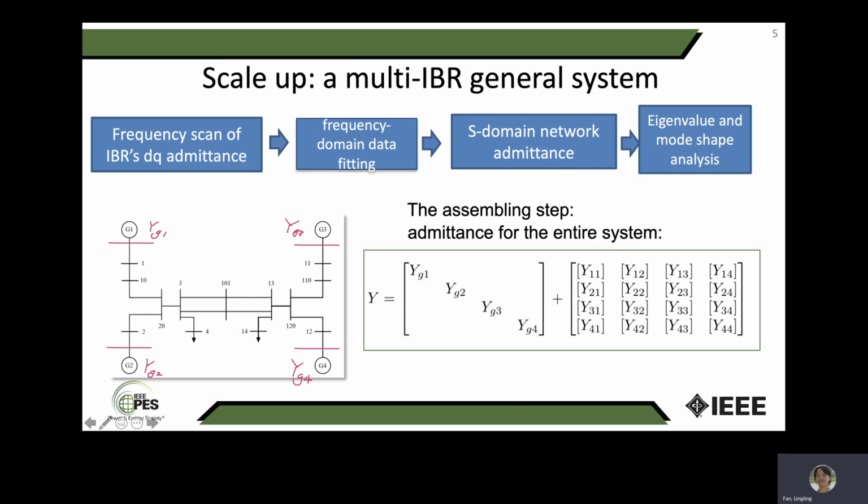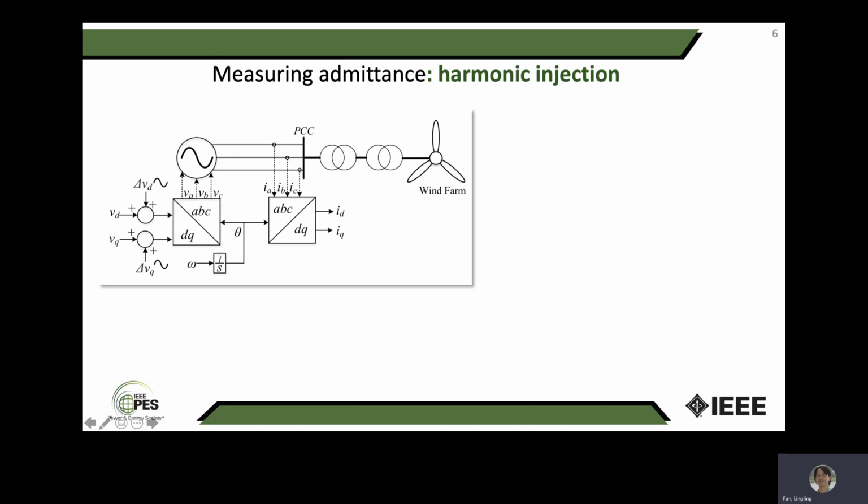Once we have this network admittance, we can attach the generator admittances, and we have a total Y bus network admittance. The nodal voltage can be written as the inverse of the Y admittance multiplied by the current injection. This is a closed loop system. We can check where the bus admittance is 0, or the poles of the bus impedance matrix Z, to find the system eigenvalues.